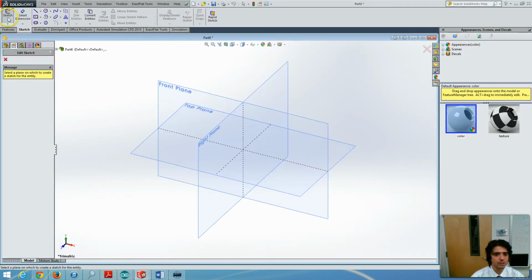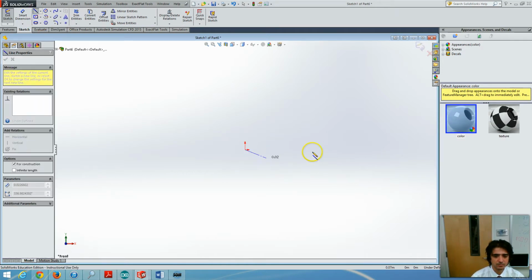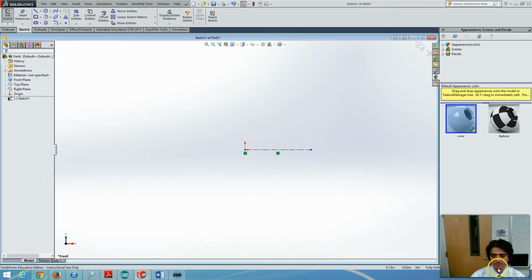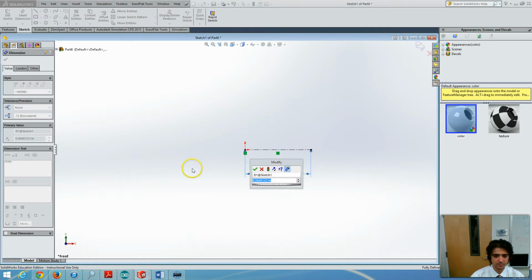So we will start a sketch, and we can do it on the front plane to have the global x and y properly oriented. We can start by making a center line. We need to be in MKS, as we are. And let's put that this is 4.5 meters. This is a giant cross section, so this is probably some earthwork cross section. 4.5 meters.